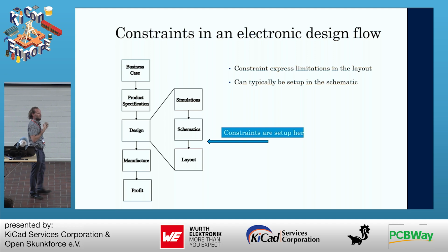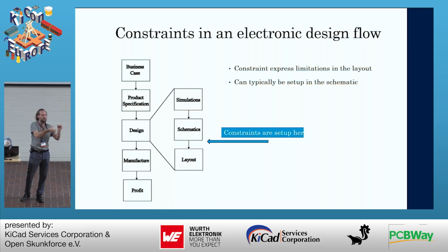But in many cases, when you set it up, you take your schematics as a starting point, because the schematics have the functionality of your design. You can look at the nets and easily say, hey, what is this part actually doing in the design? And should we have some constraints on these nets or these groups of nets or this group of the system in order to make it work correctly?